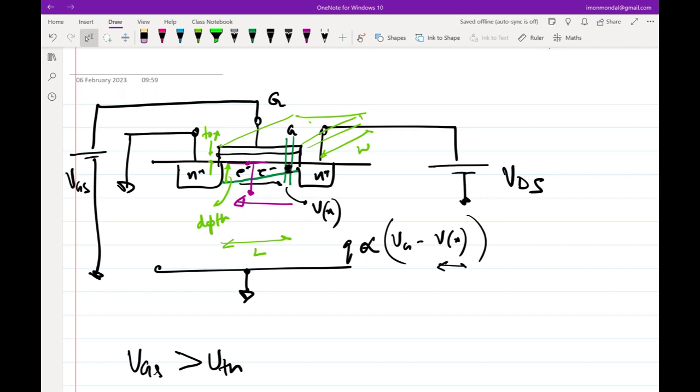It's like a Lego, right? You take a Lego block. Now you have been asked to make whatever you can with that Lego block. If you are making the Lego block, then you can decide on the dimensions, color, and so on. But once a Lego block is made, you can only change certain aspects of it. Obviously, you can put multiple of these devices together to make whatever circuit you want. But as far as the device dimensions are concerned, you can only change W and L, which means you can make the device either wider or longer. That's the only handle that you have.